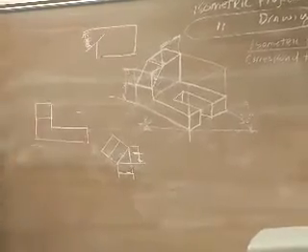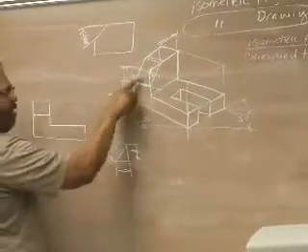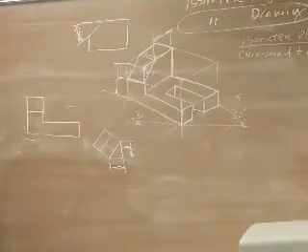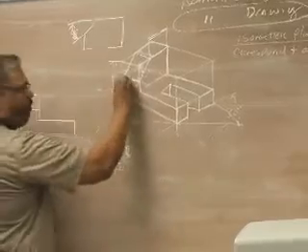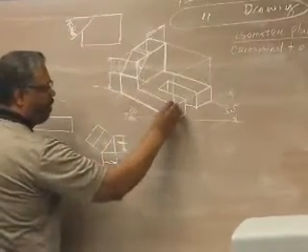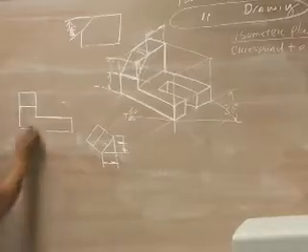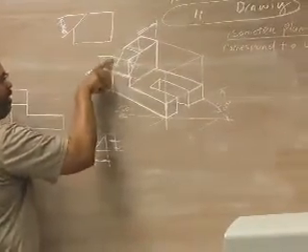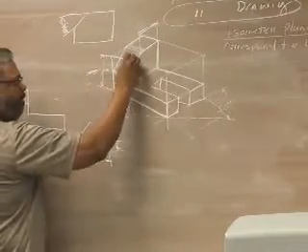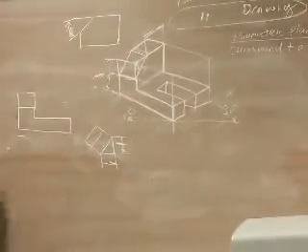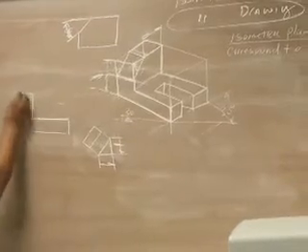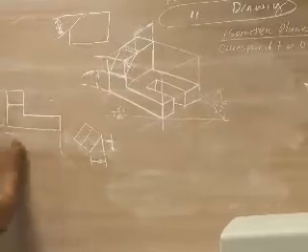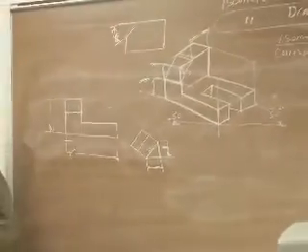So this surface, which you were talking about, is this surface laying back like that, and that's the height of that surface. So here's part of my front view is this right here, and that's what we got. Part of it, when I look in the front view, I see the surface, but the overall height of it is right there. And we connect those two, and that's the height of this object. That gives me this height right here, and then that gives me this width right here.